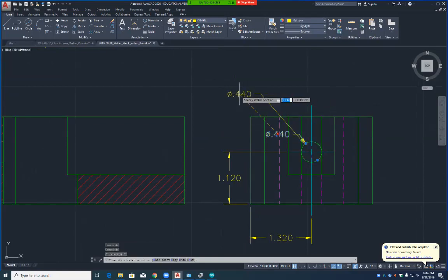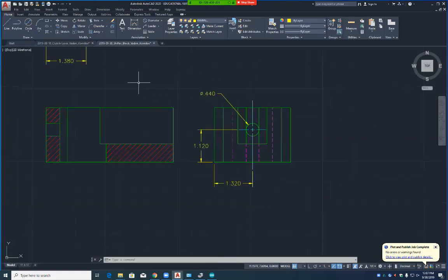And is our precision to the thousandths or hundredths now? What should they be on this drawing? I would say they need to be 3 decimal places. On this drawing, there's only one that's 3, right? So I'm going to change them to 2 decimal places, and then I'll physically go in and change the 1 to 3. Does that make sense? Okay.